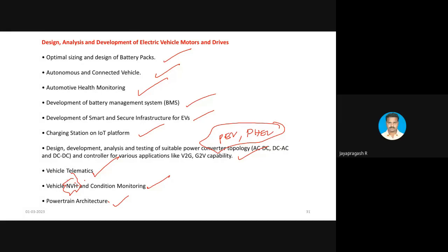Ms. Sarojini Harikrishnan has asked how to reduce torque ripple in SRM using rotor and stator parameters. That is what I said. The number of rotor poles and number of phases are among the major factors. If you increase the number of rotor poles, the rotor pole arc should also be greater than the stator pole arc. By optimizing the rotor pole arc, it is possible for us to reduce the torque ripple. I am talking about the geometry modification. It is possible by having more rotor poles.